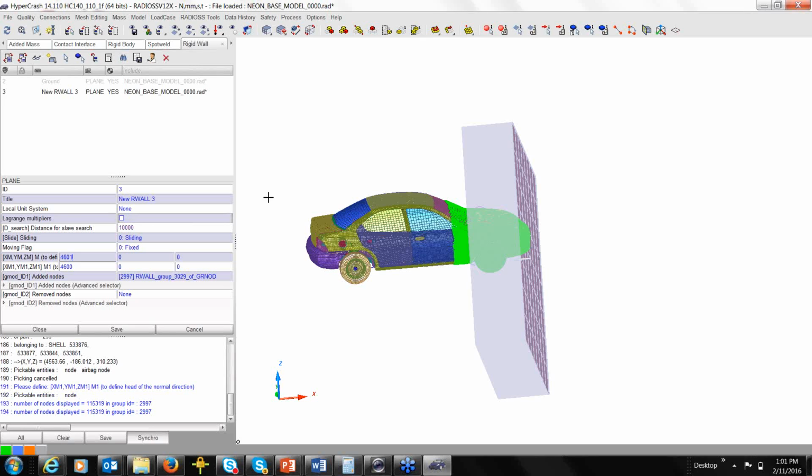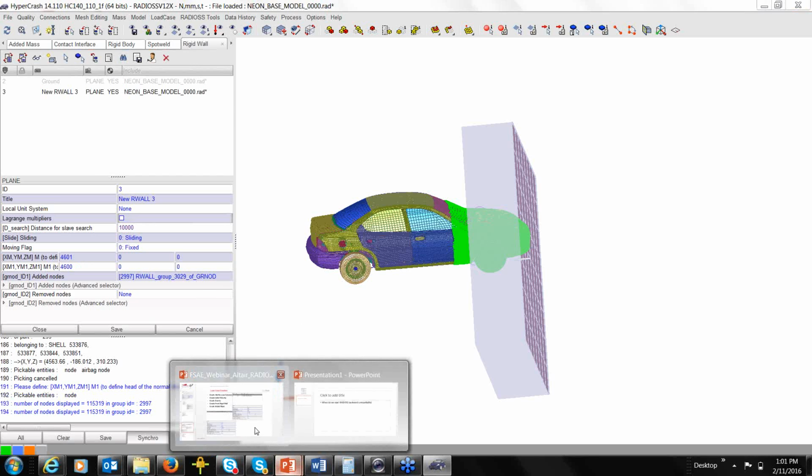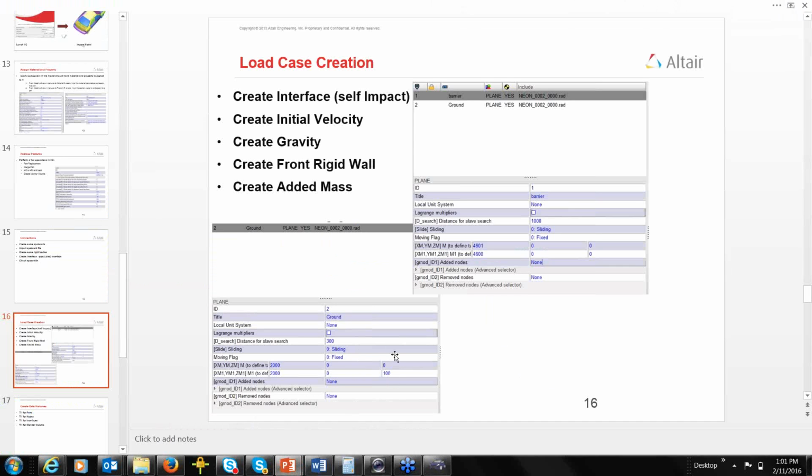When you plot your curve later on, you will see that if you waited 10 millimeters before you touch it, the vehicle is going to travel 10 millimeters and nothing will happen. You are eating time. Using valuable CPU time, exactly, CPU time. Okay. So that's the rigid wall creation.